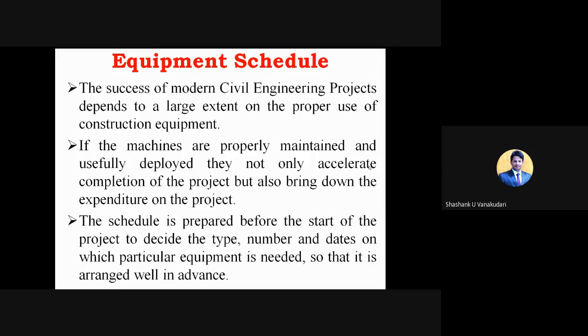Okay, and here the schedule is prepared before the start of the project to decide the type and number of equipment and the dates on which each particular equipment is needed. So once you prepare the equipment schedule, you will come to know on which date, for what duration, which type of equipment is required. So well in advance you can select or inquire about that particular equipment and bring it to the construction site, so that it will be useful to work as per the schedule.